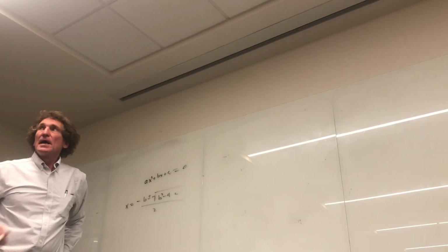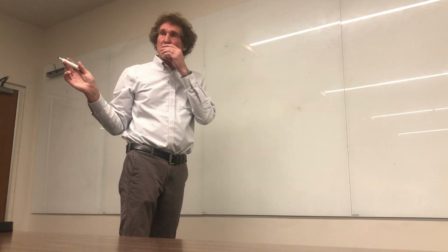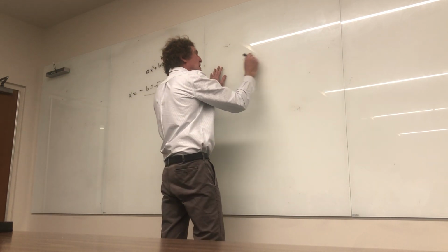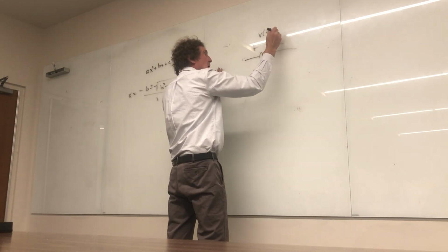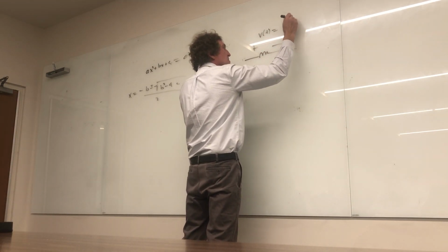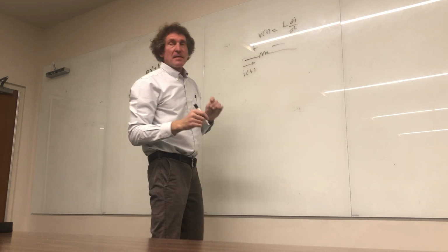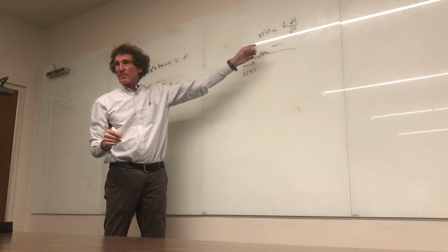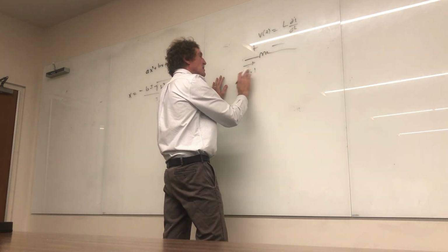All right, now back to the problem. So when we take a look at what things look like when the initial conditions are present, I'm going to do it with the voltage transforms only, because that's the way it's almost all the time put. I want you to follow me on this. With an inductor, I have a voltage v of t, and that voltage is equal to L times di dt. This is i, right? That's in the time domain.